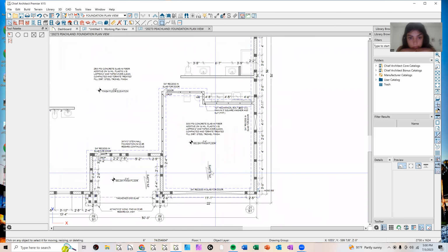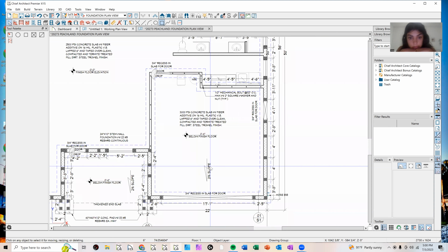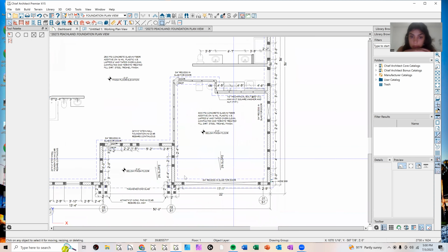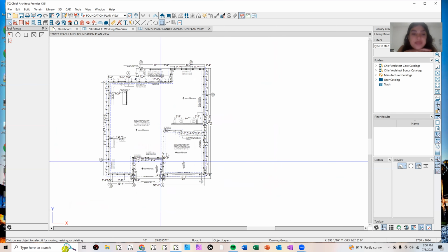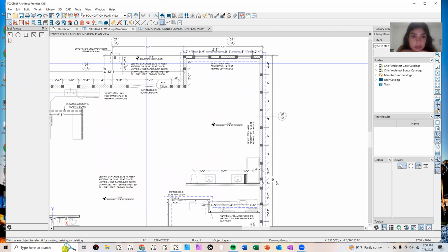This is the slope of the concrete in the garage. You want any water that gets in there to slope out, because garages are waterproof, but in case water gets in. So they run a 2% slope there. You're going to run a 2% slope on all of your porches. Front porch, back porch, is going to have a 2% slope.